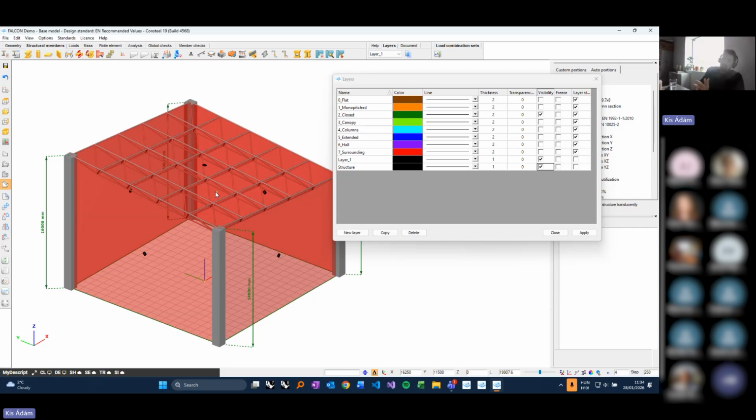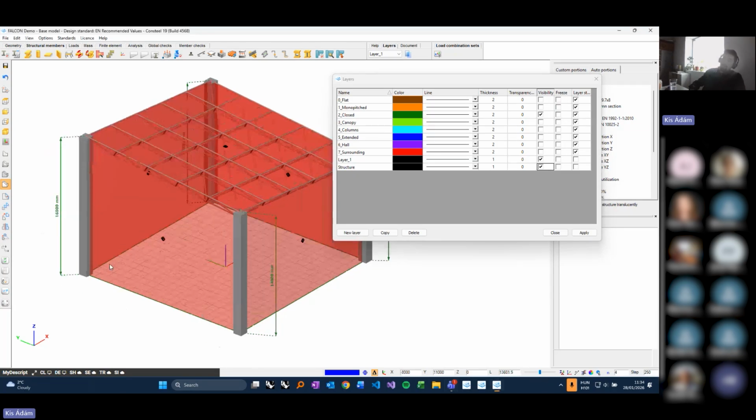Why? It is really important to understand that CFD simulations, like any simulation, are finite volume based, using a finite volume mesh, which requires volumetric geometries. Therefore, we have to model everything around our building which we want to consider.